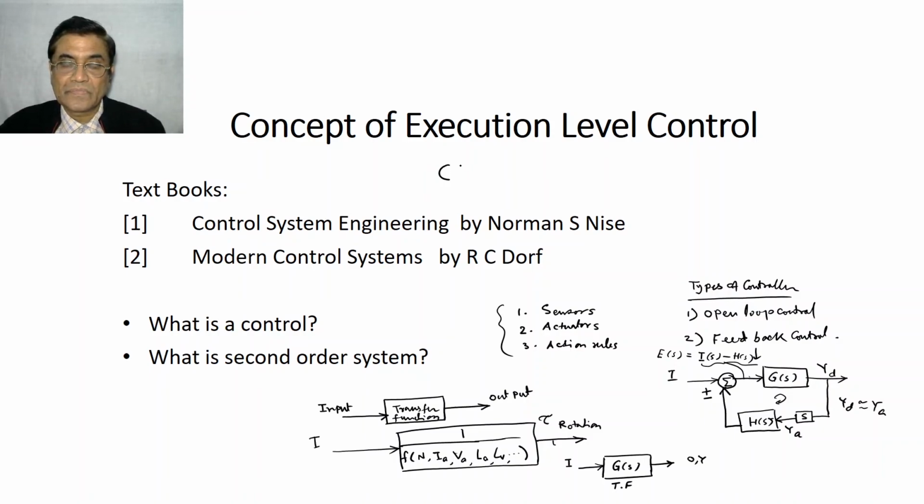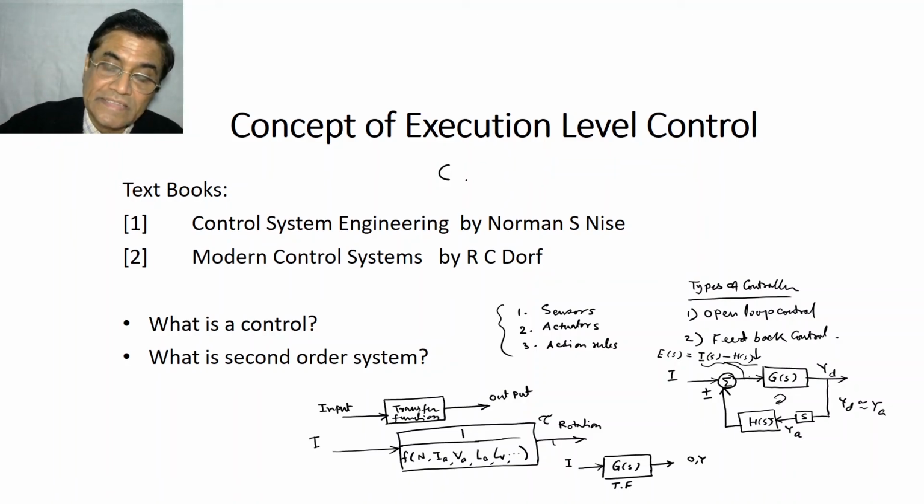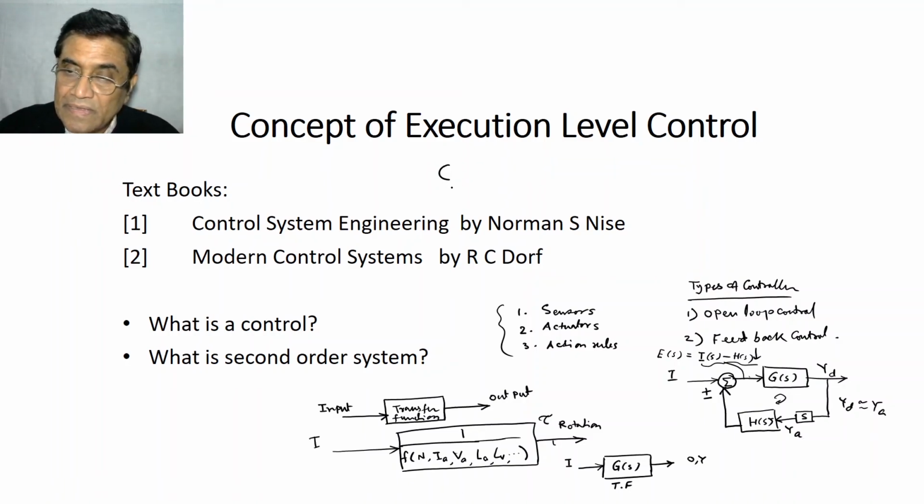It will start from somewhere, and if this is a given trajectory, my controller is expected to give some kind of C, and depending on the sophistication your controller has, it could be something like this, or it could be exactly this, exactly matching the desired value. We'll talk about all this. So the controller actually ensures that the desired state is being achieved.